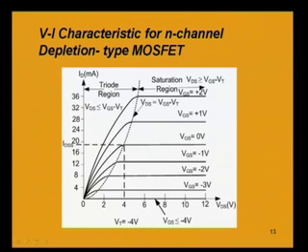So, the drain to source voltage is equal to Vgs minus Vt. Mind it that for this particular device under study, the threshold voltage is negative. So, if Vgs is equal to minus 3 volt, we take minus 3 minus Vt, again minus 4. So, minus 3 plus 4 means 1 volt.